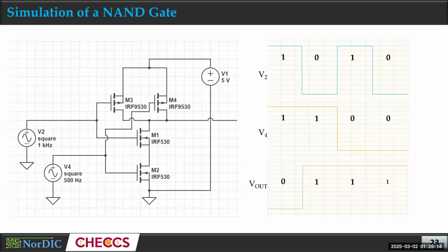Now make the gate connection first. You see, one PMOS gate and one NMOS gate connected, and another PMOS gate and NMOS gate connected, and these will be your two inputs, input one and input two. Look at this connection. This gate will be connected to this one, one PMOS and one NMOS. So look at the circuit: the gate of one PMOS is connected to the gate of one NMOS, right? Exactly.